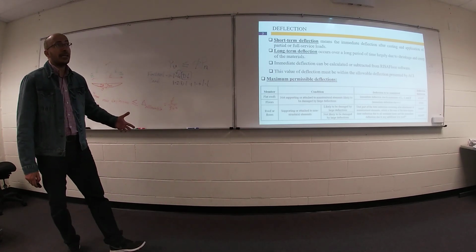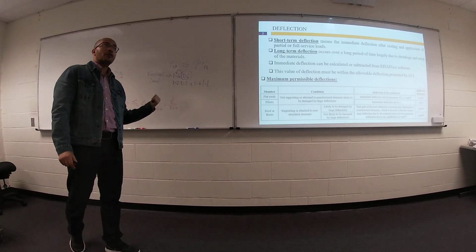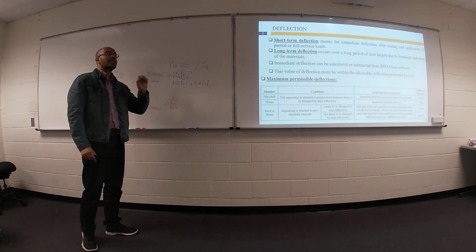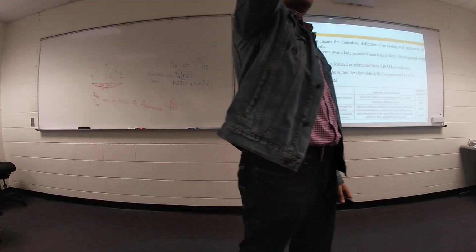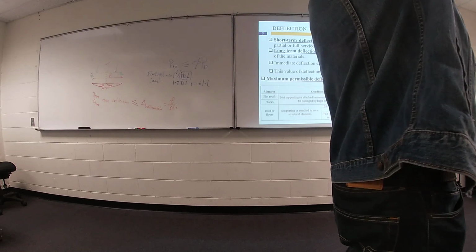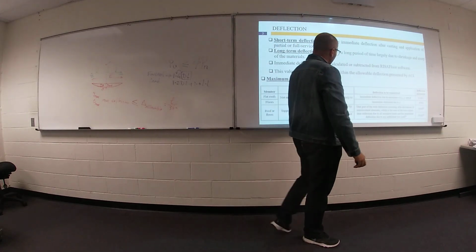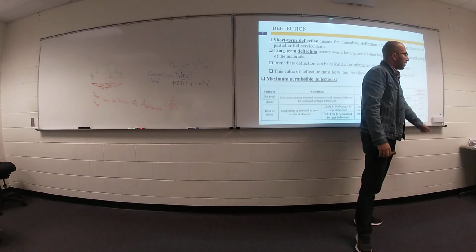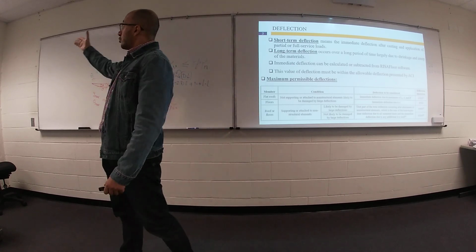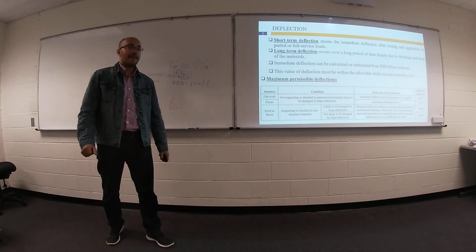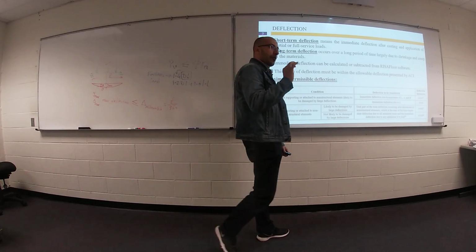So next time we will solve this slab on RISA, and I will let you know how to get your deflection. Your maximum deflection for this floor, I think, will be at the middle. Once you get your deflection, compare this value by L over 360. Which L for this area? The longest or the smallest one? The smallest one.